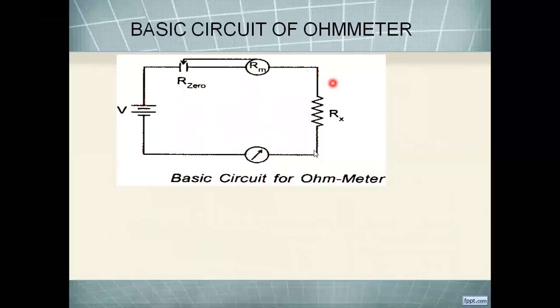This slide. Here, please don't get confused that it is a capacitor. It's not. It is a resistance. So let me join it. It is a resistor. Here we have placed the arrow mark. It states that the resistance of this resistor is dependent on the meter resistance. Before going for measurement, we have to make sure that there is full scale deflection when we short circuit these two leads of the ohm meter.